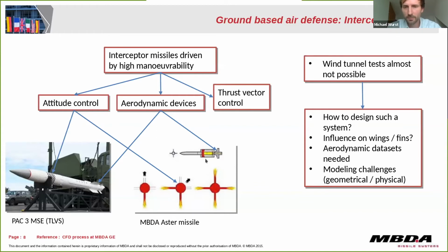One question is, for example, where we should start with our simulation. So should we model the nozzle, or could we start with some boundary conditions here? Then what model should we use? Should we use single flow? Should we use chemical reacting flows or two-phase flows? Should we consider the altitude influence, that these systems depend on the flight altitude? And should we also consider different operating conditions, like full thrust, or only 50% thrust?